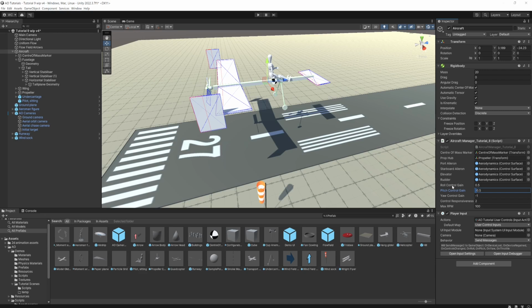We've completely changed around the aircraft, but with a few simple changes to control surface gain and the angle of the tailplane, we've got an aircraft that balances and in theory does the right thing. Next up, let's try the dynamics. So we're going to release the aircraft from its fully rigid state and just allow it to move around the centre of gravity. Notice we haven't moved the centre of gravity. It's exactly where it was before in the other aircraft. Let's try that.